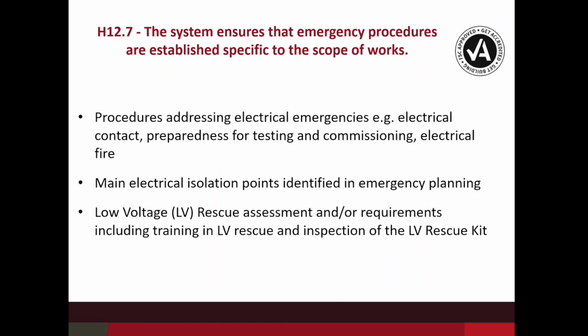We look for things like electrical isolation points and identification of those, so that potentially in an instance where the electrician is not necessarily available, that a main switch or something like that is identified, usually on some sort of plans, so that we can turn it off. A normal person with no electrical experience can go and basically flick a switch, enacting the emergency requirements. That's not mandatory. And again, there are a number of ways in which companies can manage this in terms of planning. And that's how we look at it from a perspective of, we look to what the company defines and then we audit against that.